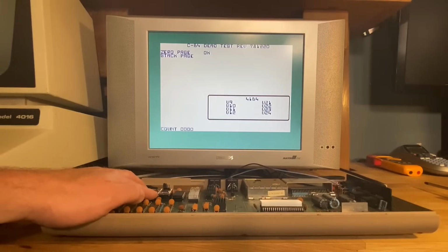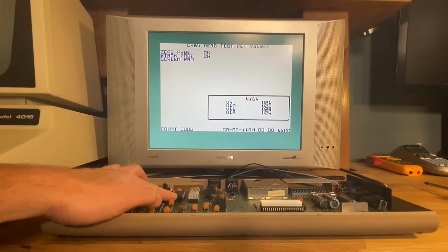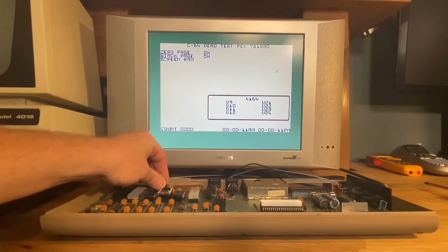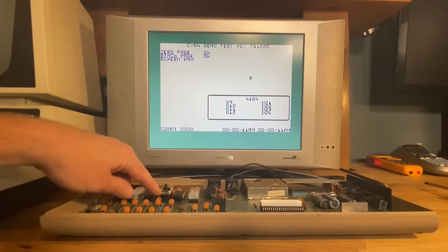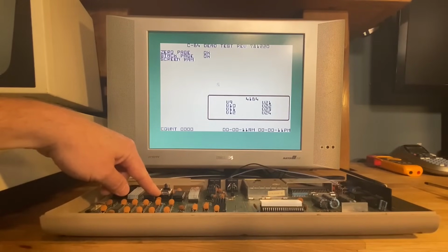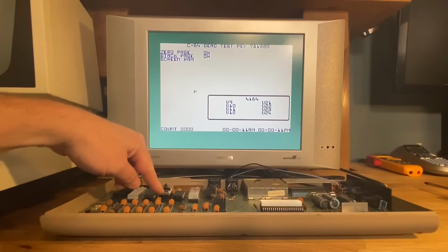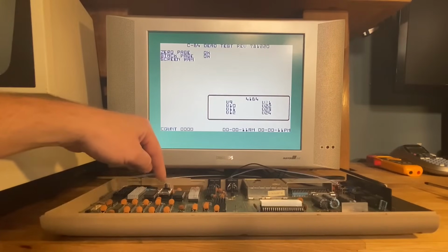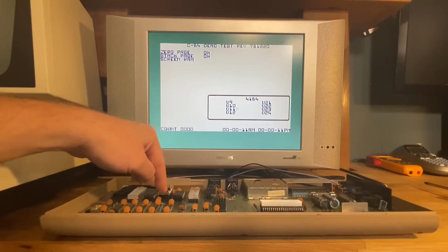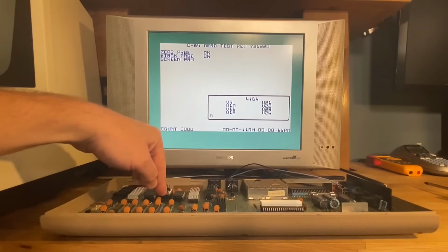So far we've seen software-defined retro ROM acting as a 2364 replacement. The character ROM on this C64 is a 2332 with 2 different chip select lines, and I have the character ROM image already on software-defined retro ROM in image 2. So we'll swap it over from the kernel socket to the character ROM socket, and we'll reinstall the Jiffy DOS kernel in the kernel socket.